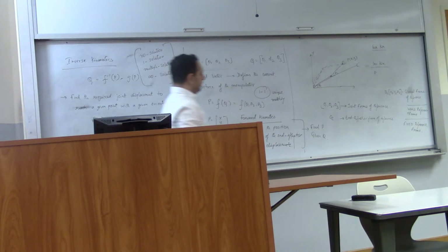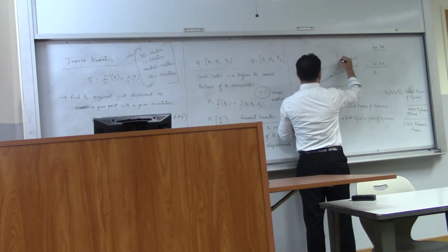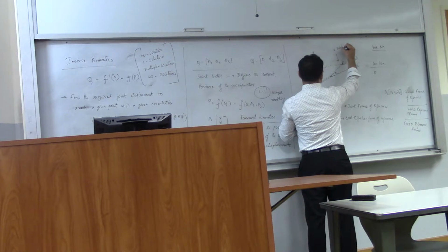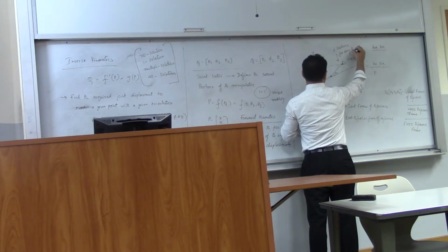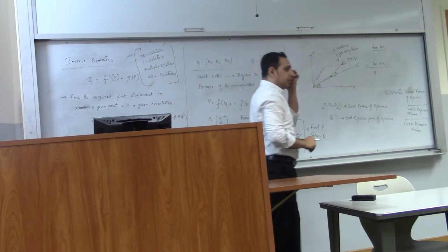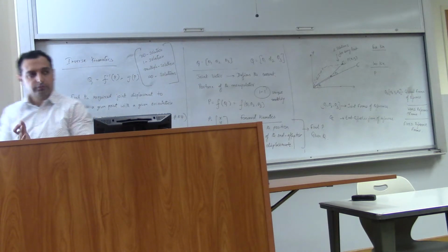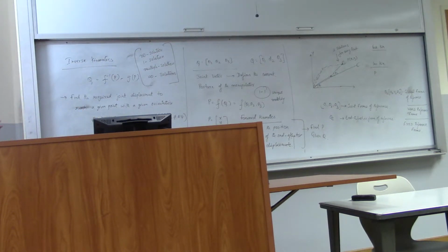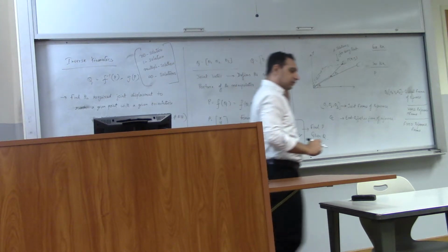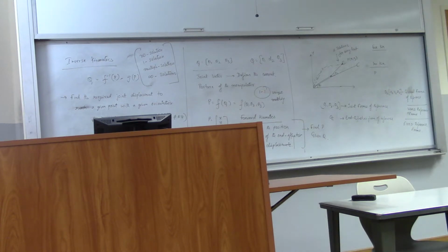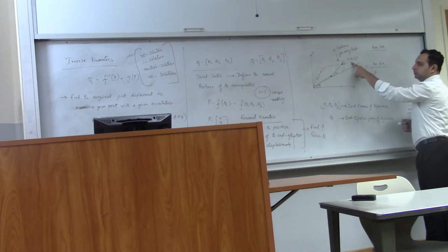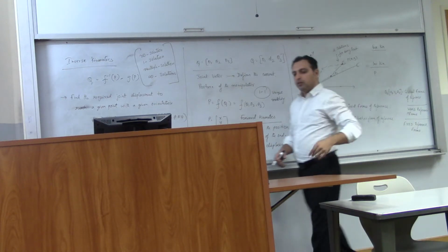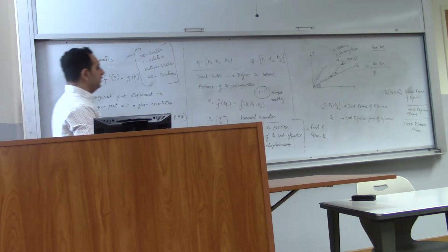Okay, so basically, here you have two solutions for every point. Obviously, except the boundary of the workspace. Is that clear? Why is the inverse solution a little more complicated as opposed to a forward kinematics problem? Forward kinematics, it's one-to-one. If I give you theta 1, theta 2, there is only a unique position. But if I give you B, there can be multiple Qs that will get to that position.